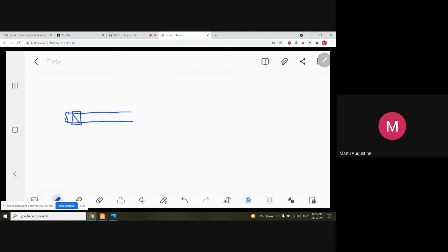There is a bearing here. It's not shown in the figure, but it has to be there. Otherwise, how would the shaft be held in air? So even if the line diagram is not showing something that is obvious or which has to be logically there, you just consider it like that. Okay. So on two bearings on both the ends, the shaft is connected and the stiffness is given as KT1 dash on both sides. J1 is the inertia of the pulley number one.